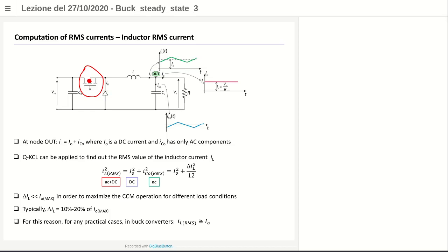Okay. Sorry about that. It happens when you use cut and paste, and the error was at the beginning, and you can have all the symbols wrong. But pay attention: the power MOSFET symbol has the arrow that enters the device, quite different from the analog symbol of the N-channel MOSFET, in which the arrow exits. So take note, pay attention to this fact. I reloaded all the slides with this symbol modified. No changes in what is written under the figure.